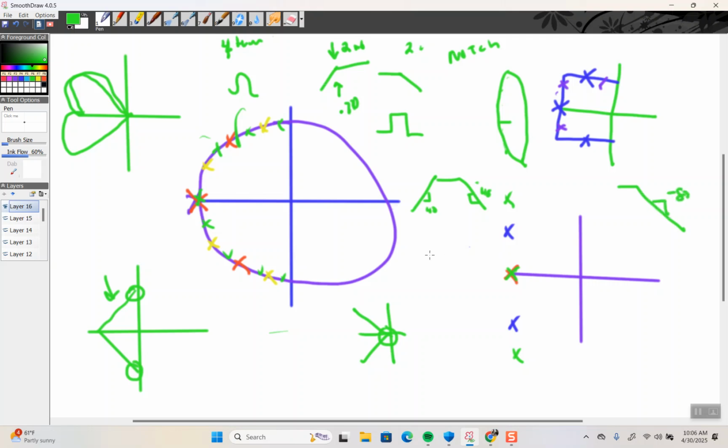Well, with the notch, it's the same thing. You would get 40, 40, because it splits it. When I first thought about it, I wanted a fourth order filter on each leg. No, it splits it. And if you put in an odd number, oh my God, don't do that. Don't use odd numbers. It works for the high and the low, but for the bands, Python will just give you what it thinks is best. It won't let you do odd. And how could it? Because you've got two things going on, so it can't be odd. All right.